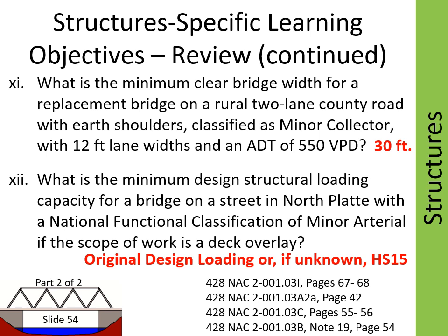The national functional classification is given as minor arterial. North Platte is over 5,000 population, therefore this is an urban area. See page 42 of the standards for urban area. Therefore, the correct table is table C starting on page 55 with the bridge standards on page 56.